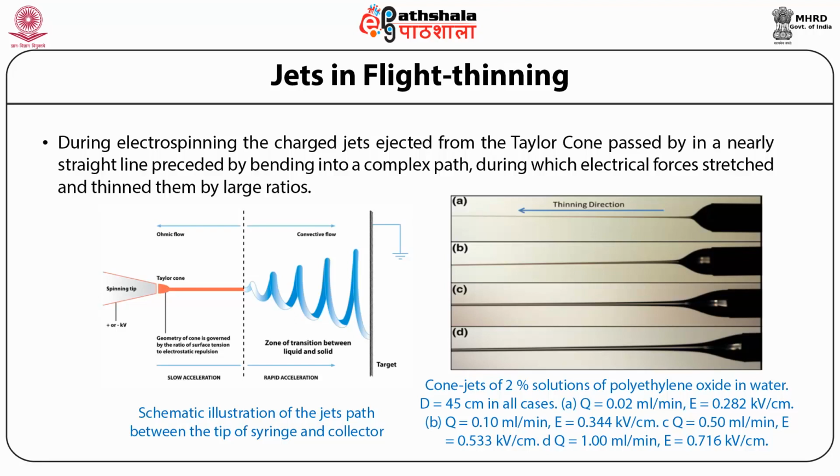Several attempts have been made to explain such trends in electrospun jet operation as a function of fluid and operating parameters under experimental control. Within certain limits, for a given fluid, there exists a range of driving voltage V and flow rate over which the electrospinning can be maintained stably for a longer period. The electrospinning process contains an electrical circuit, so one can measure as well the current flowing through this circuit. The characteristic length over which the initial dramatic thinning of the jet takes place can be identified with the axial distance where advection and conduction current are equal.